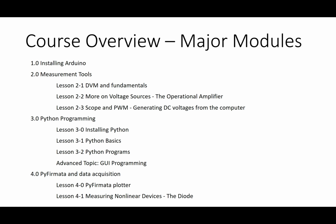And then we will use our oscilloscope to take a look at a voltage that changes with time and the pulse width modulation output of the Arduino, which is what is used to generate DC signals. And we'll show you how to generate a DC voltage using pulse width modulation under computer control.